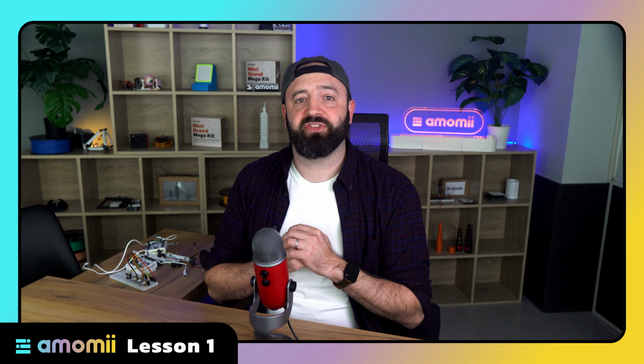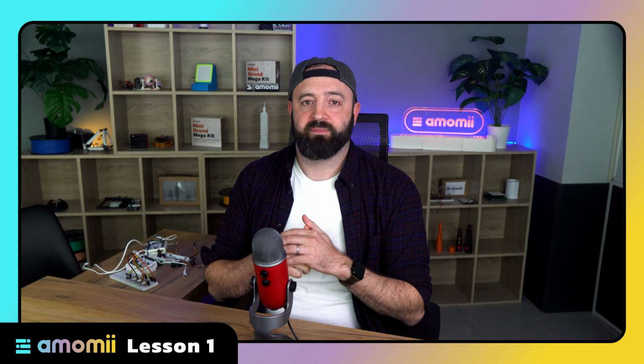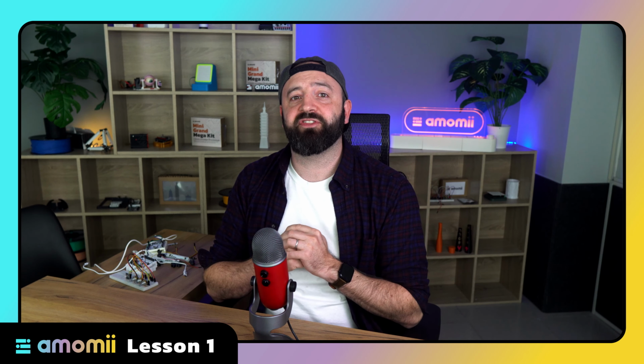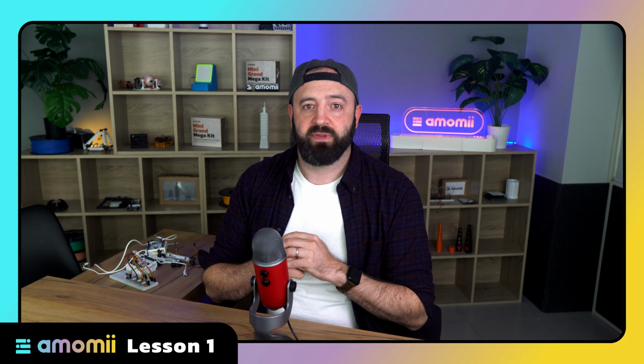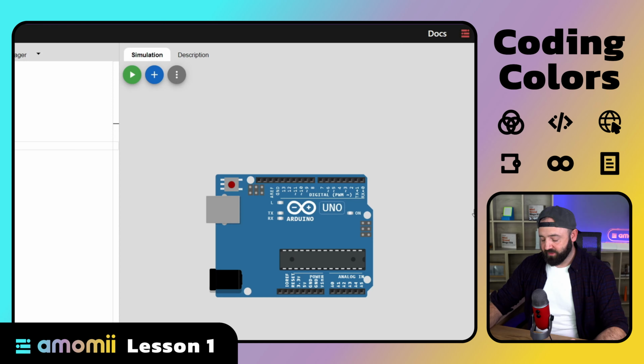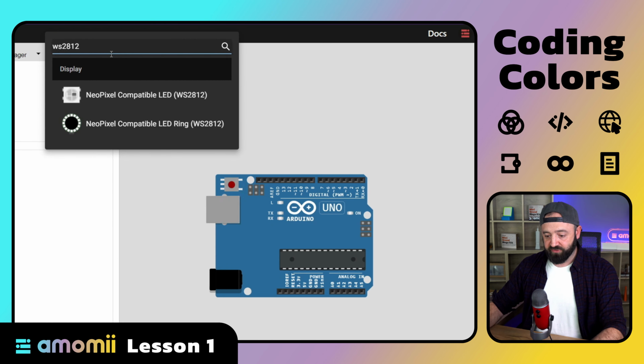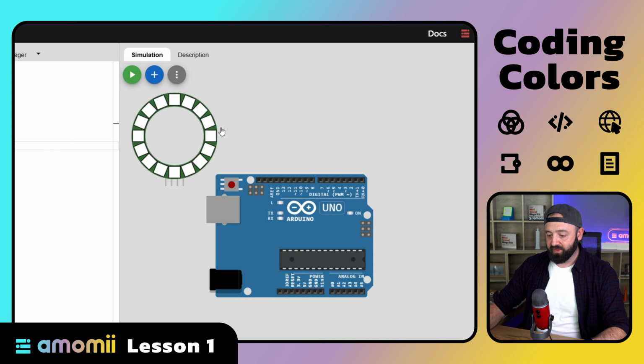Now that we're acquainted with the software, let's build the circuit. We'll first build the circuit using the online simulator because that makes it very clear where the wires go. And then we'll move on to the real thing. In the hardware section of the simulator, hit the plus button and type in WS2812, and that will bring up these two options. Select the NeoPixel compatible LED ring, and this will open up.